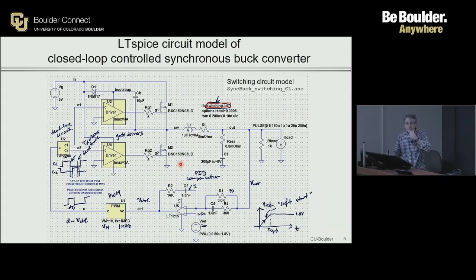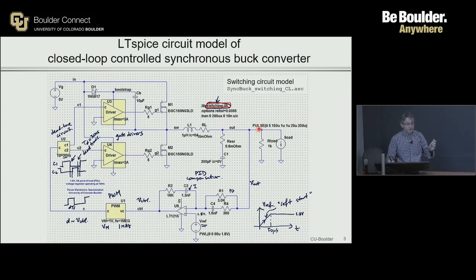But voltage would drop? Regulation voltage would drop? That is not necessarily the case. In fact, I would also encourage you to run exactly the same example with 200 nanoseconds of dead time and see whether the voltage is still regulated at 1.8 volts. The magic of feedback comes into play here. No matter what detailed stuff happens right here, feedback, up to its limits, is going to be able to overcome that and still provide the output voltage regulation.